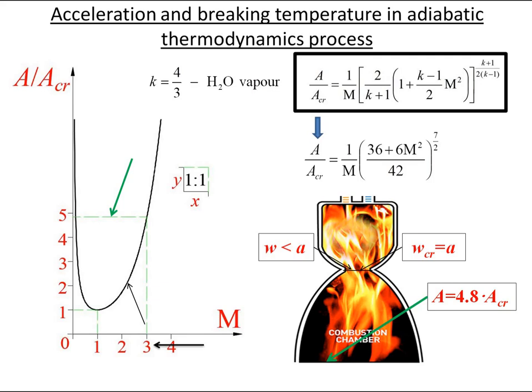Energy conservation comes from the fact that gases enter the critical cross-section area with a higher temperature and exit the nozzle with a lower temperature. The reduced gas temperature is transferred into higher kinetic velocity of gases, which propels the rocket with higher velocity and higher efficiency.